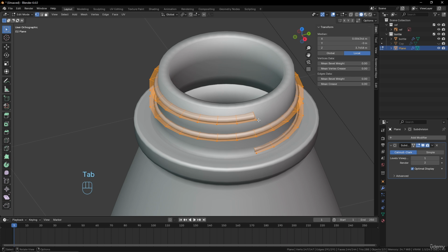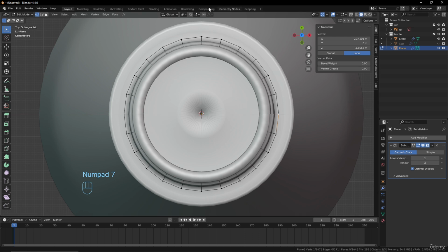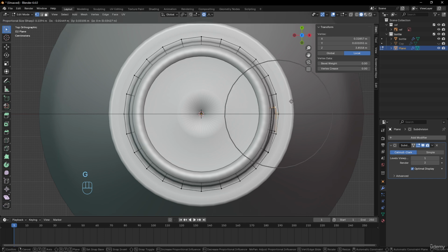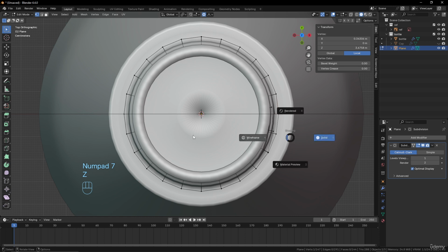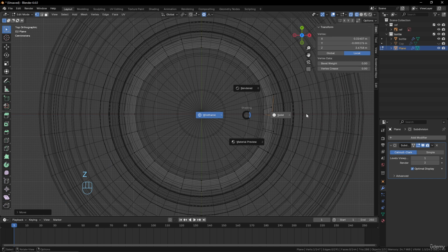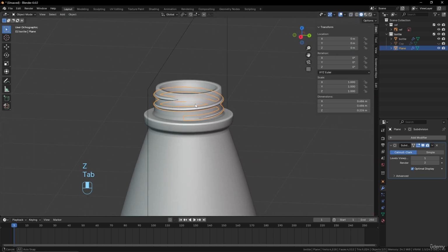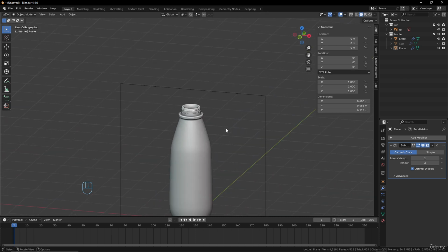Now I will have the entire shape, and now I can manage the end and the beginning of it just by going on top here, enabling the proportional editing with connected only and with the sharp option, and now you can put here the tip inside and the beginning here inside as well. Okay, we can go in here in wireframe mode, to see more what we are doing, and now we have something that goes progressively inside and outside. Okay, good. So we have our first screw.